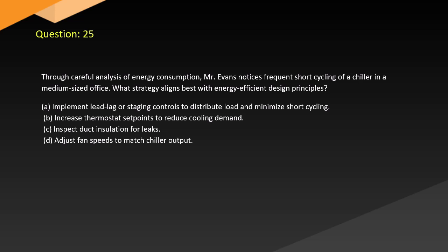Question 25. Through careful analysis of energy consumption, Mr. Evans notices frequent short cycling of a chiller in a medium-sized office. What strategy aligns best with energy-efficient design principles? A. Implement lead-lag or staging controls to distribute load and minimize short cycling.